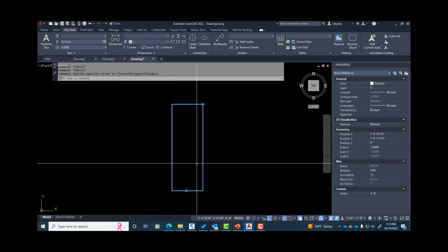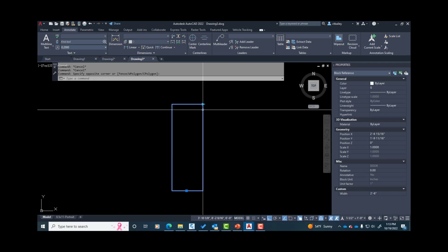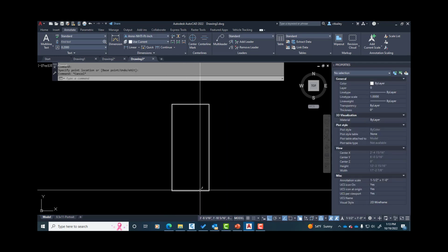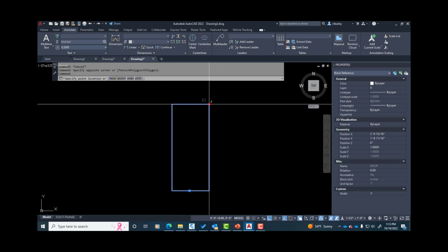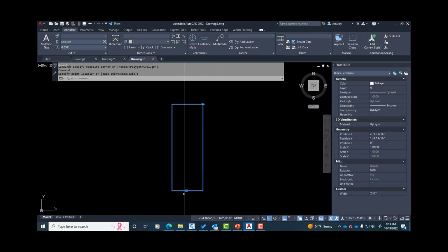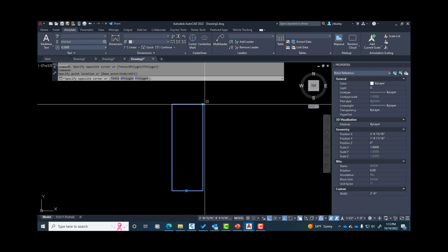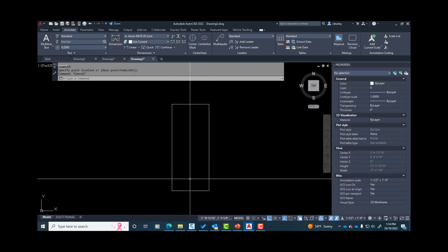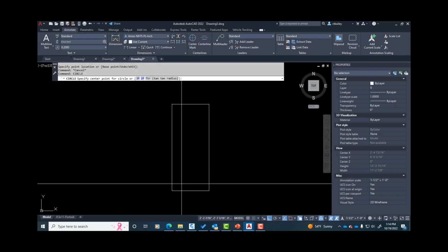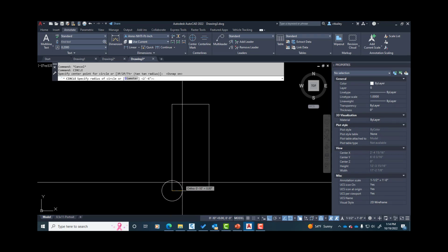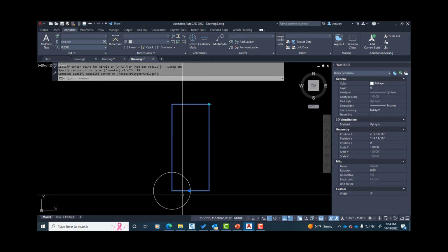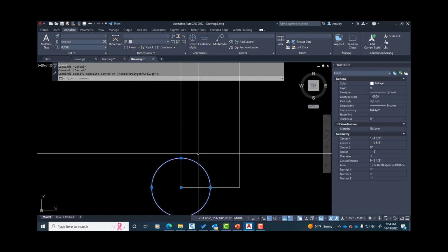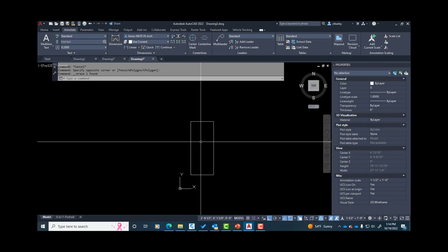And because we're holding those geometric constraints, everything is nice and constrained perpendicular. And you'll also notice the base point is still moving as well. So if I go all the way to the end, 36, half of that is 18. Okay, so if I were to do a circle at 18 inches, and I selected it, looks like we've got a problem. It's always good to check. Right? So let's go back in there. 36.